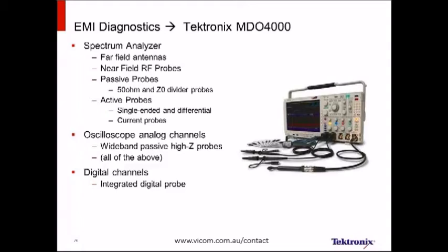One of the curious aspects of the digital side is that in our implementation, we can have individual thresholds per pin on our digital input, meaning if you needed to create your own bus of a wide variety of signals, you don't have to have a single threshold to determine high or low for one pod. You can do that on a pin-by-pin basis. At the same time, we can decode up to 4 buses simultaneously. So if you needed to look at RS-232 and SPI and RF at the same time, we could do that.